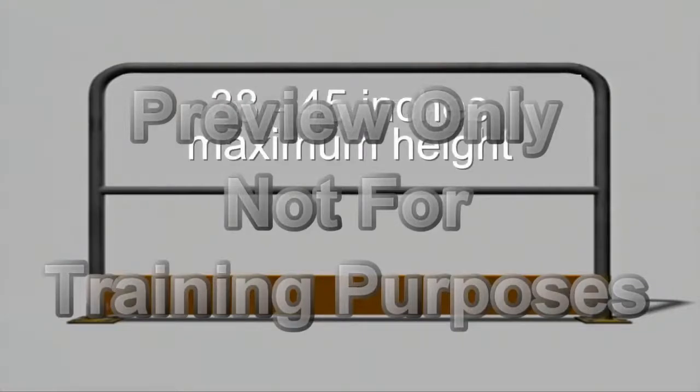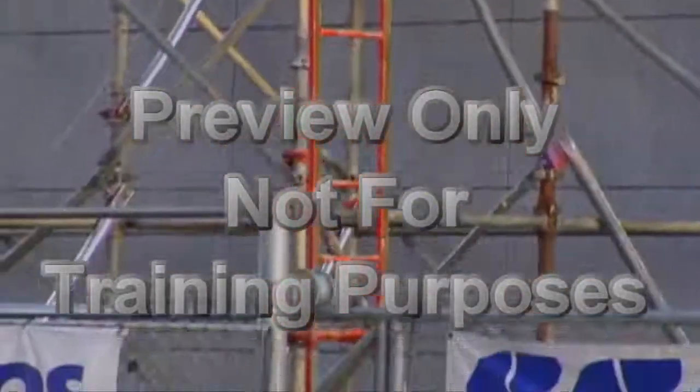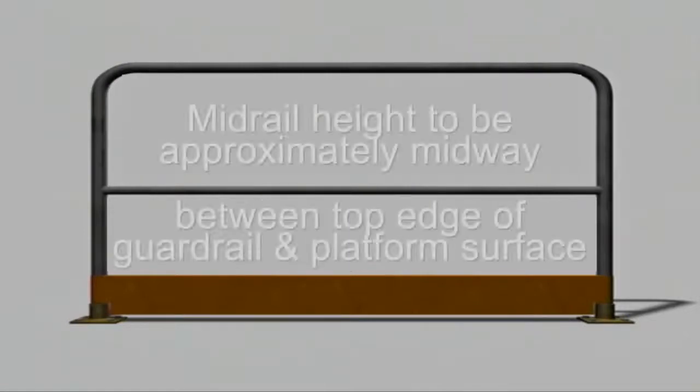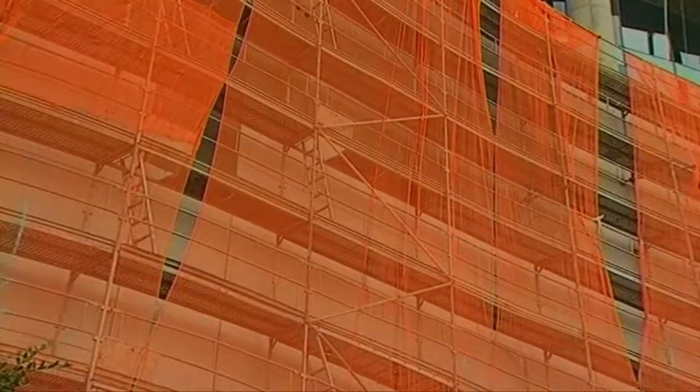The top edge height of top rails must be between 38 and 45 inches. Mid-rails, screens, mesh, intermediate vertical members, and solid panels must be able to withstand a force of at least 150 pounds applied in any downward or horizontal direction at any point along the mid-rail or other support member. Mid-rails must be installed at a height approximately midway between the top edge of the guardrail system and the platform surface. If utilized, screens and mesh must extend from the top edge of the guardrail system to the scaffold platform and along the entire opening between supports.